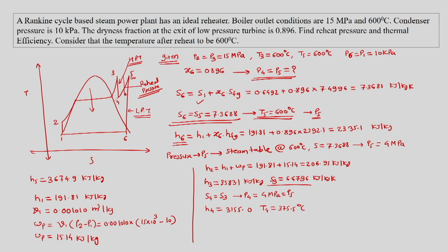Using these conditions we can find the location of point 4. By one match, S6 equal to S5, we can identify the pressure, and by the other match, S3 equal to S4, we get the temperature, and maybe also whether the point is inside the dome or outside the dome. We will go ahead with the next example.